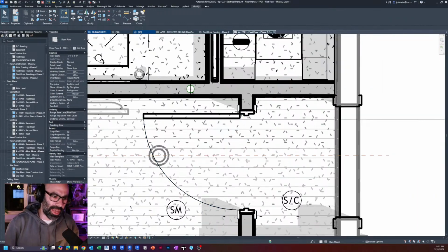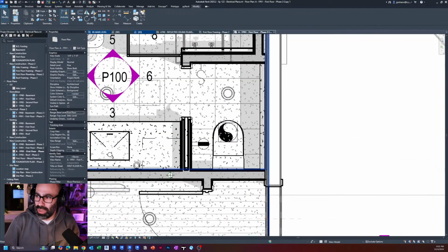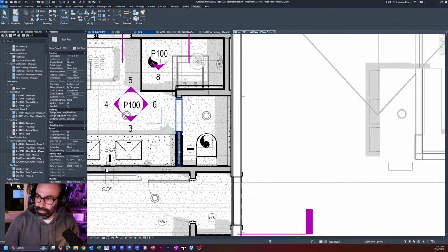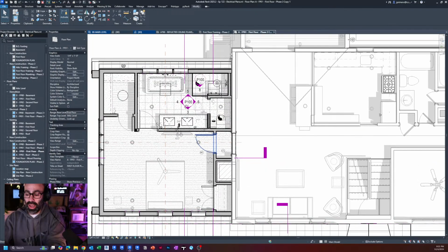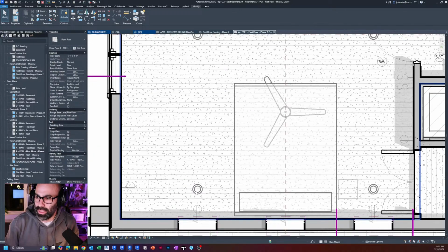And even though it's an underlay and you can't actually select it, so to speak, you can actually connect wires to it. Okay, so that's basically how I'm currently setting up those electrical power plans. Again, there are different ways we can talk about, but right now that's working for me. And what's cool about it is when you graphically set it up right, I just quickly made this view, it can be a really simple way to approach electrical power plans, and creating them is much smoother than all the other workarounds we've done in the past. And again, you can even connect wires to these from this view.